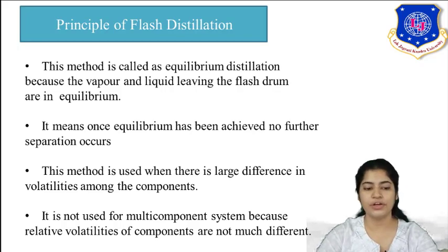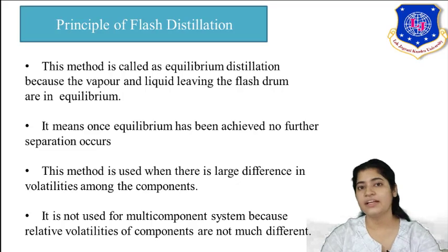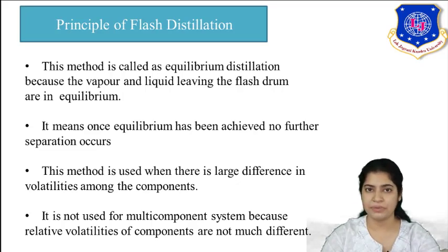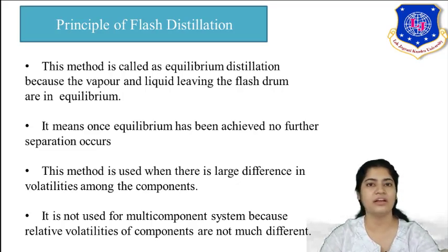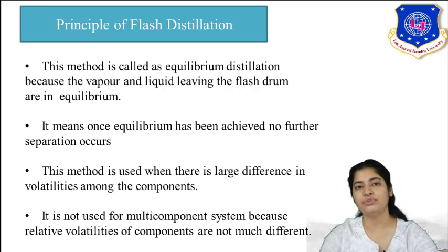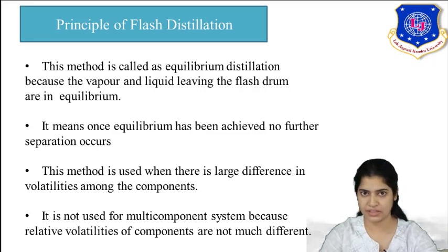It is not used for multi-component system because relative volatilities of component are not much different. So I can state that this method, flash vaporization method, is used for binary components only. So if I have to distill my multi-component system, then I have to use fractional distillation method.